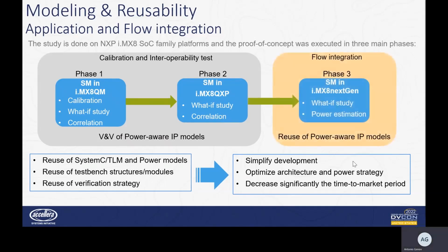In the last phase, we have reused again the model on another higher performance SoC, which is in its very first stages of development, to prove the utility of this kind of analysis. Thus, we were able to extract power estimations for specific use cases during the design specification, which is long before the creation of the RTL model.